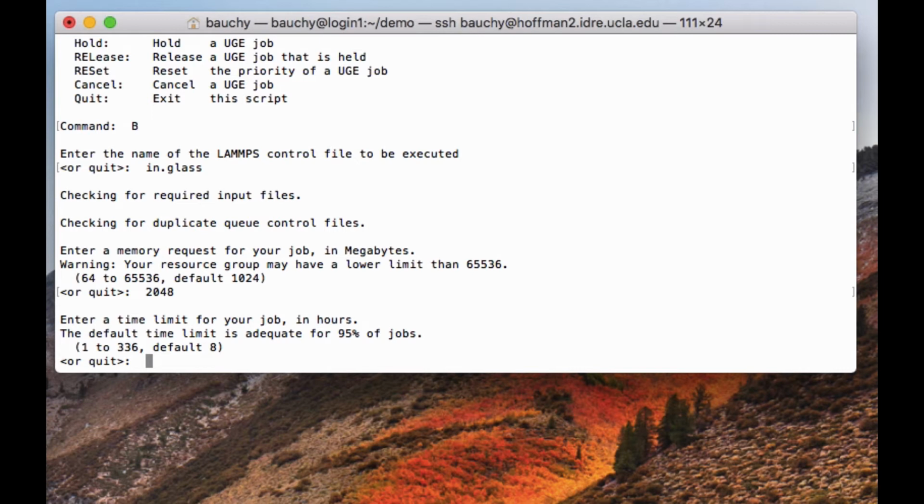So it's always good to request a simulation time that is as low as possible. But on the other hand, you need to make sure your simulation can finish before the time limit. Otherwise, the time limit might be reached before the simulation is done, and this will cause the simulation to instantly stop, even though it has not finished.